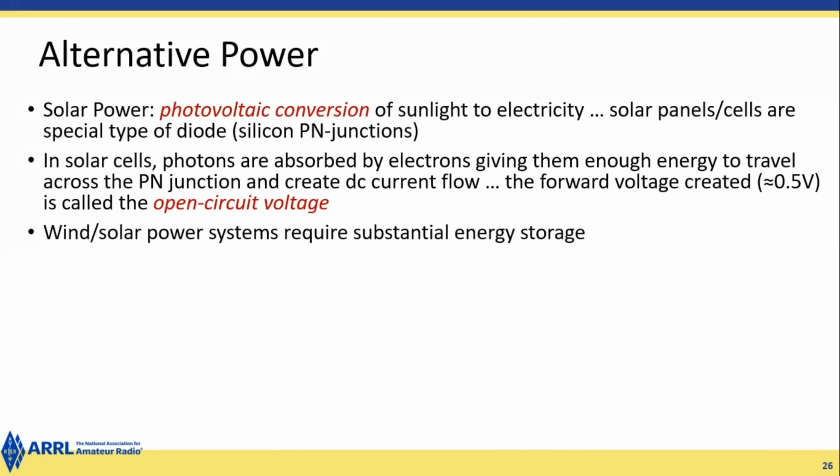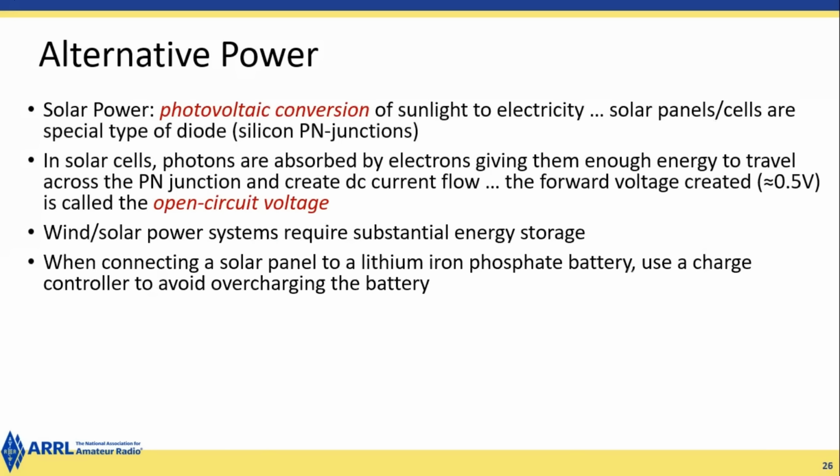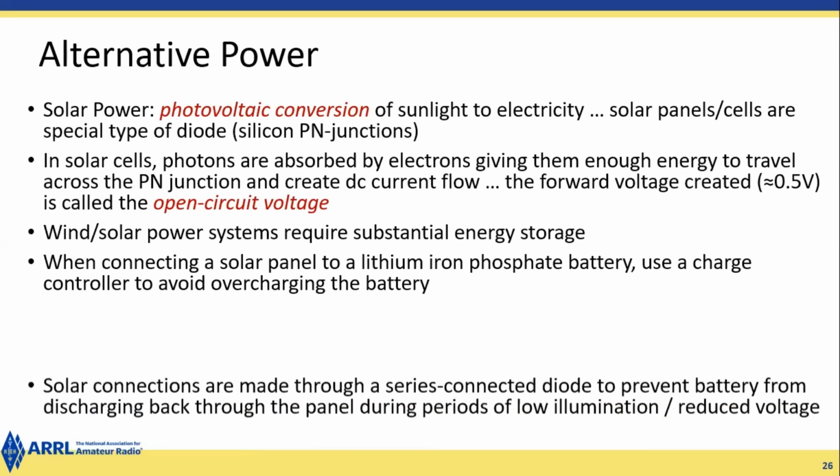Wind and solar power systems require substantial energy storage. When connecting a solar panel to a lithium iron phosphate battery, use a charge controller to avoid overcharging the battery. You want to make sure you use the proper controllers. You need something between your solar panel and your batteries as a solar panel charger.